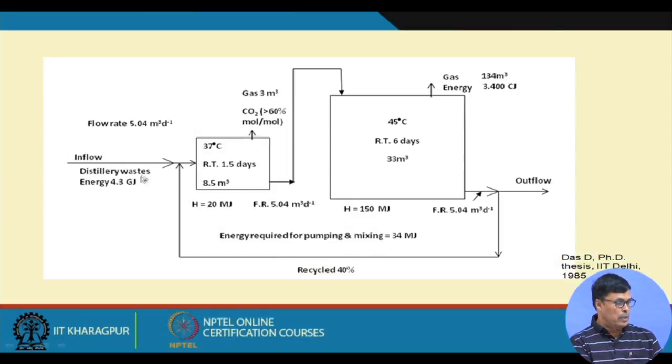Now, this is the biological process. I told you this is operated in 2 stages: this is acidogens, this is methanogens. In the acidogenic process, the retention time is 1.5 days, and in the methanogenic process the retention time is 6 days.